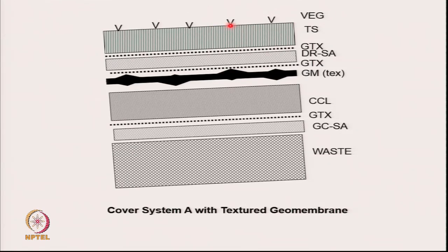This is the traditional hazardous waste cover: topsoil and protective layer, drainage layer, geotextile as a protector for the geomembrane, compacted clay liner. So this is a critical interface, compacted clay to geomembrane, delta is low. If it was smooth, it would be 8 to 12, but it is textured, it is, what did you say, 14 to 16. But let's look at the top. There's also the interface between the geotextile to geomembrane.